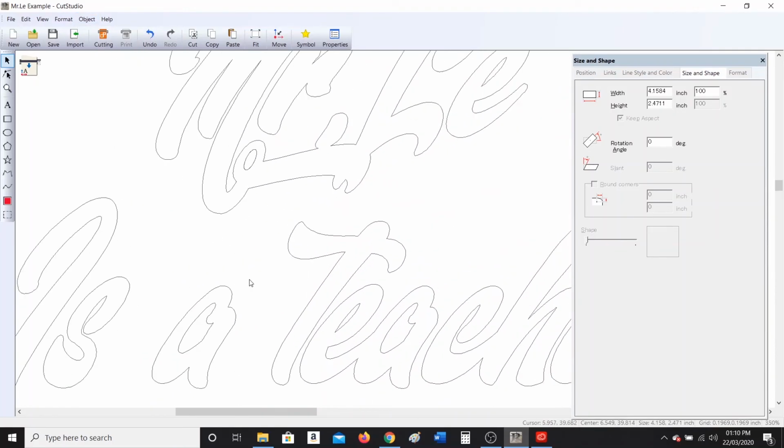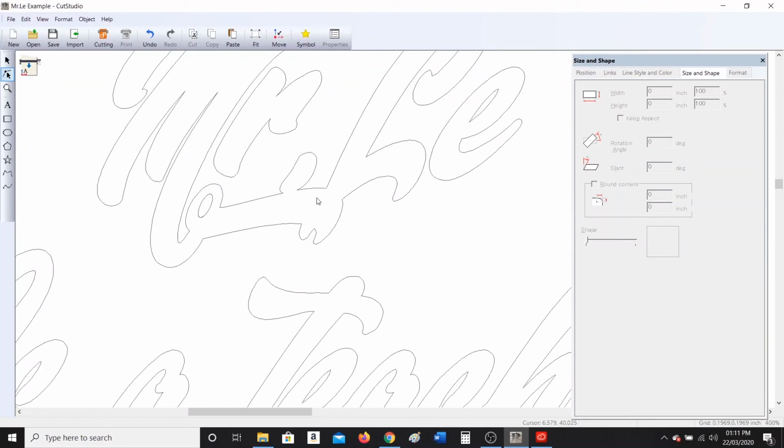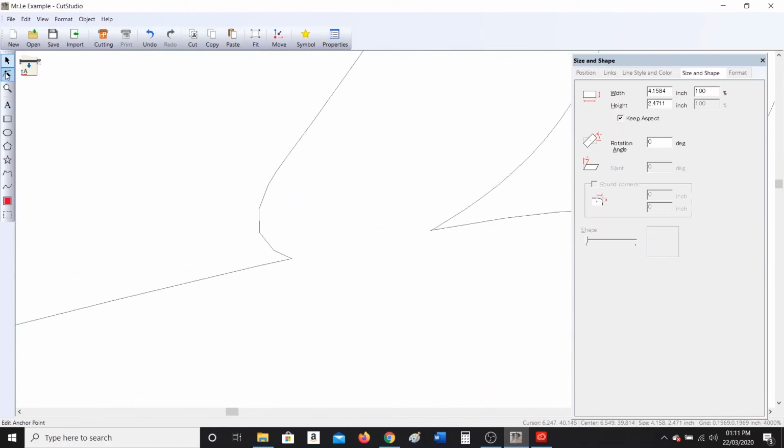Let's say I want to specifically edit something with this font. So if I click edit tool and I click on it and nothing's happening, well, if I want to fix something, for instance, let's say this guy right here, I want to make this dot its own thing. I gotta right click on it. I gotta make sure that I'm on it. Oop, select tool. Right click, I'm gonna convert to polyline. Bang. And then now if I use this edit tool, now I have points here.